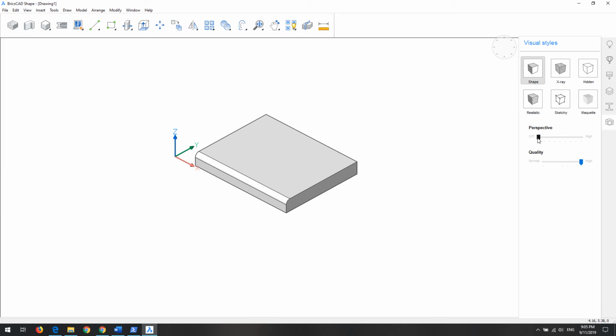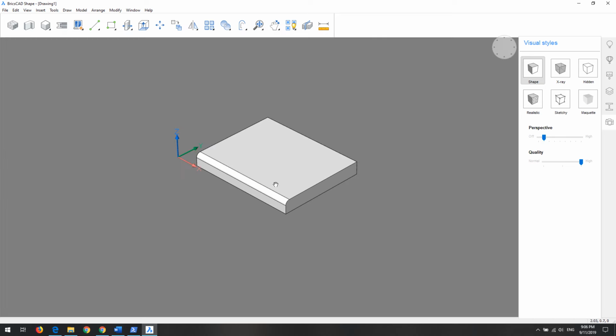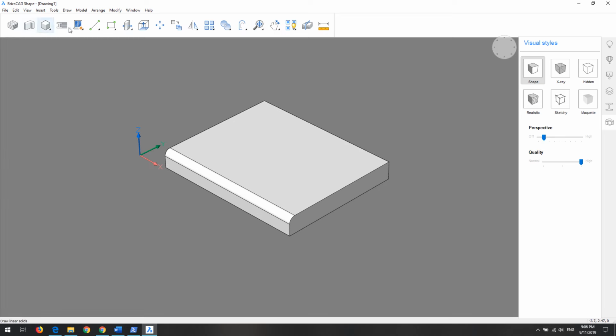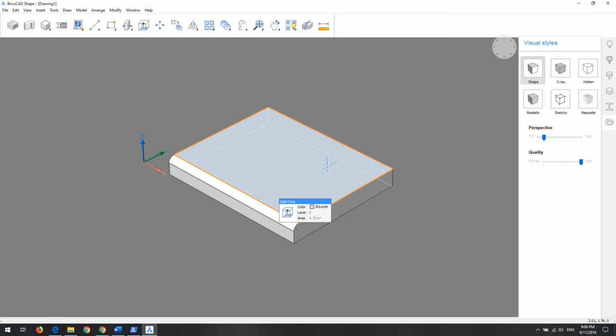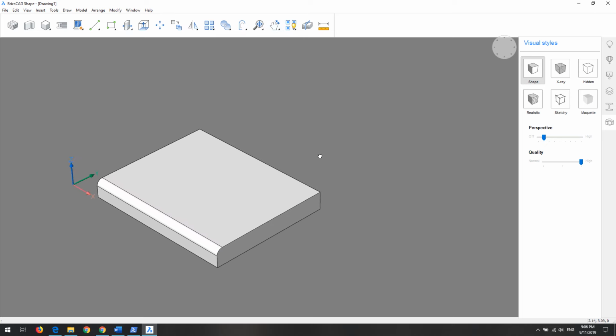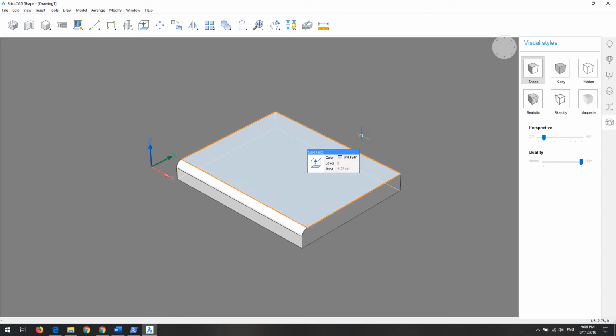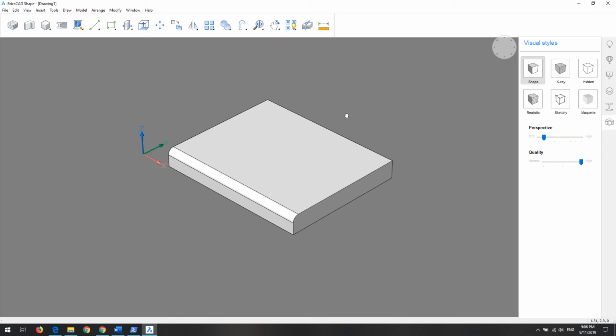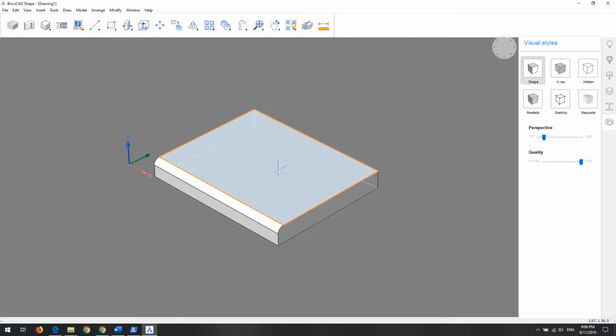Alright, let's switch to a little bit of perspective. Here we can press the escape key to come out of this pan tool. You use the mouse: if you just hold the middle mouse button and move the mouse, you should be able to pan the view.